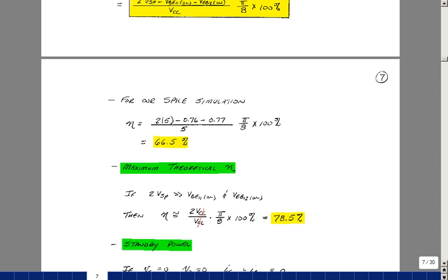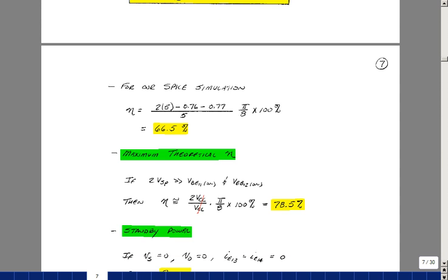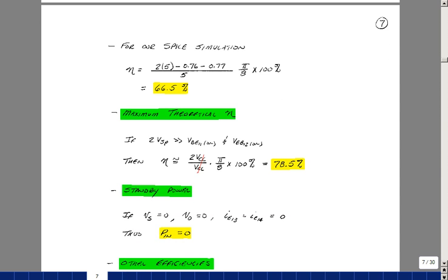We don't normally listen to things like that, although some people do, but usually we're at a small fraction of the maximum power out. The real advantage of this structure is that when the input is 0, the output is 0. So you really can't calculate efficiency because it's 0 divided by 0, but definitely the power coming in is 0 because we're not drawing any current from the two power supplies if we're not putting out any voltage.